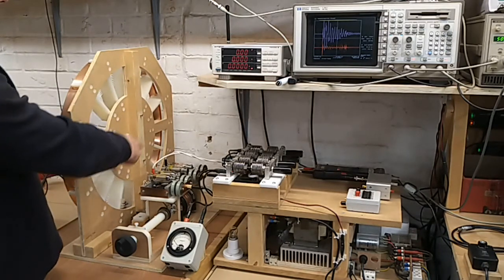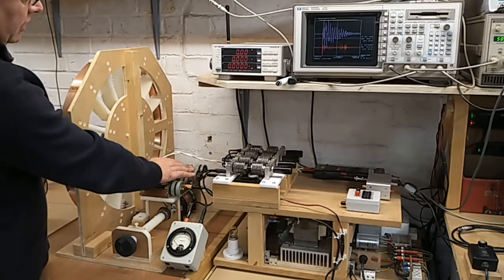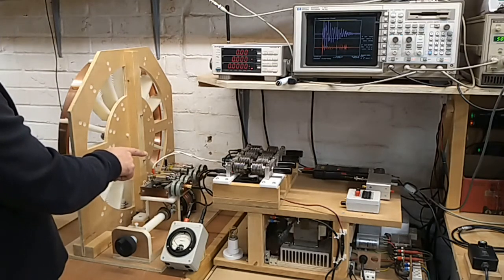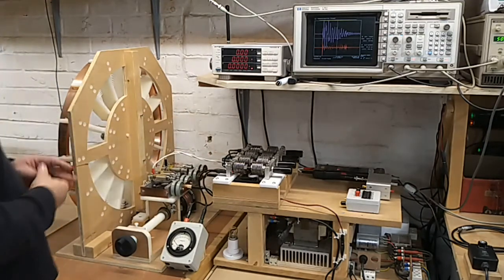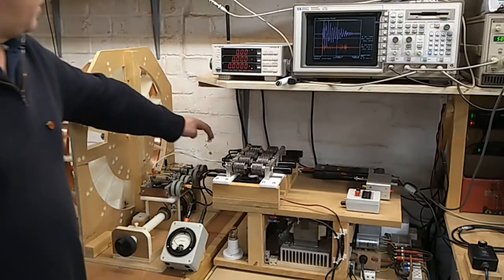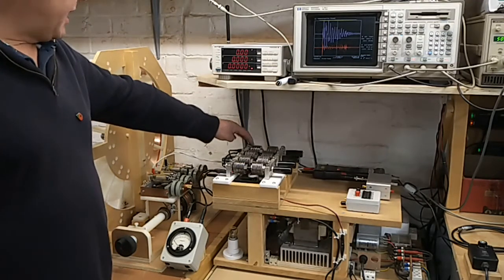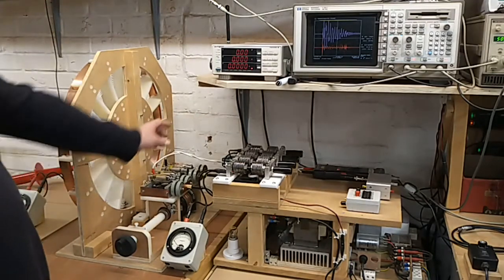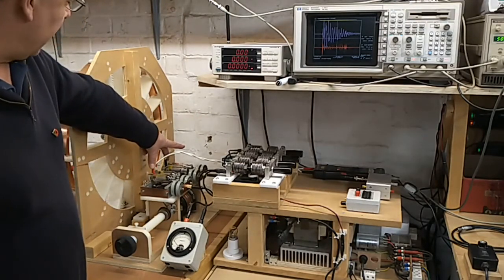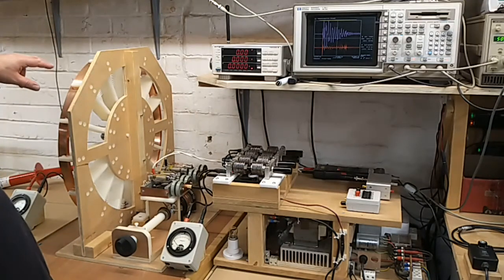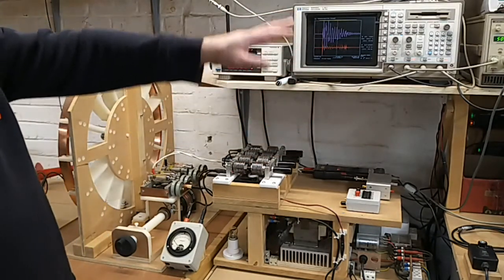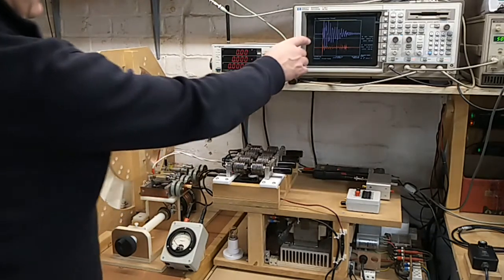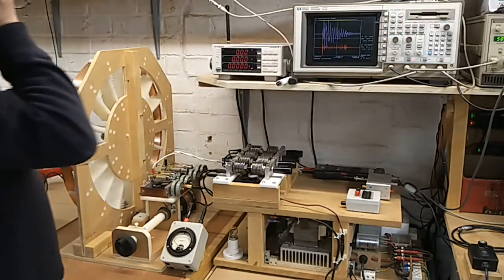Out of the primary, again on the other side, through the shunt, another 4.7 nanofarad set of capacitor bank here, out the lead, through a Tektronix current probe, although we're not seeing that at the moment, and then back to the spark gap. And as before, we are measuring the high voltage potential actually across the copper strap primary. We're using a high voltage probe which is connected to a frequency meter, which is also connected to the purple trace on the oscilloscope.